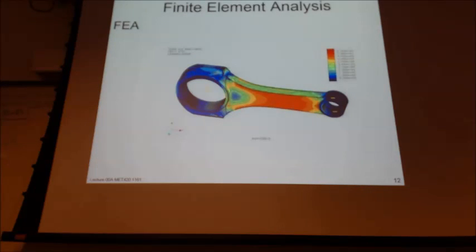So you maybe overload it and underload it, or change the modulus from a minimum to a maximum, and see how that affects your part in your analysis, and you can correct for that. The mesh, making sure that it's accurate and that it's what we want to call a good-looking mesh. You're looking for triangles and squares, right?